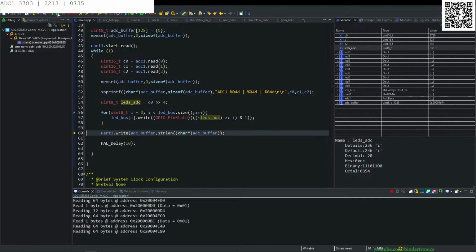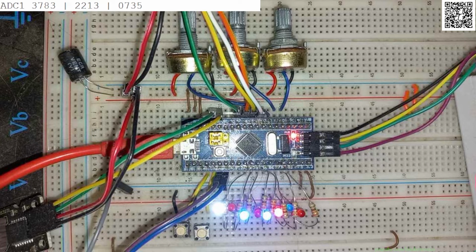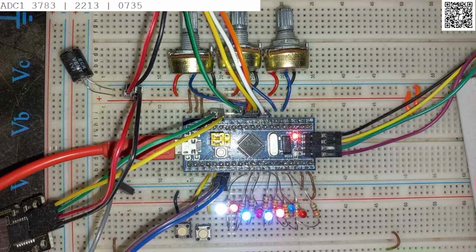111.011.00. Okay, so we resume. So this is the value we expect, a 111. We don't have a 111, we have a 11 and then a 0. I'm suspecting that one LED is dead. I'm going to pause the recording and just double check the LED. Now, as you can see, the LED is on. It was just a loose connection. So we have the correct value here.